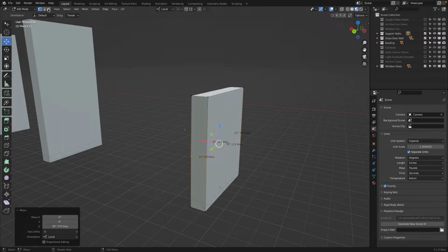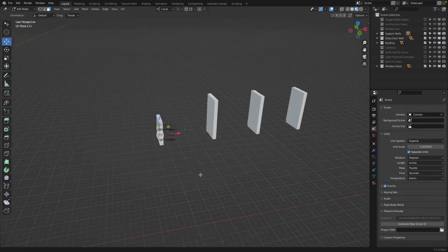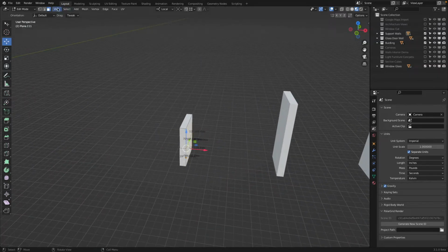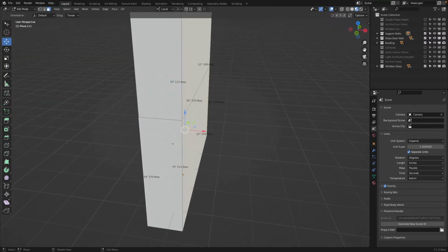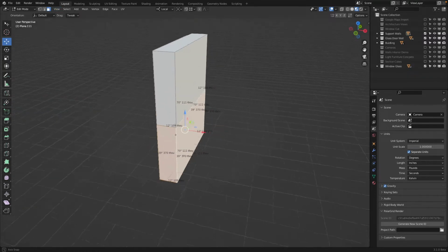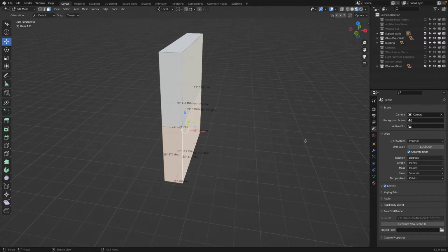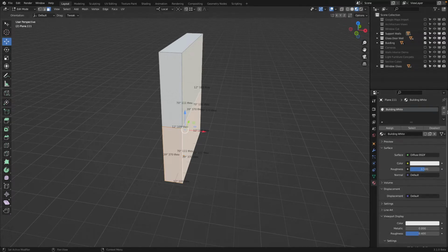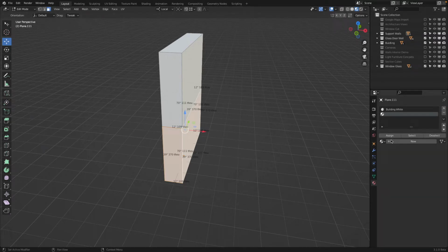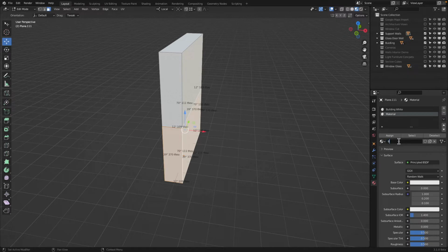Switch to here. So this is the material preview. Then I can select, whoa, careful, these materials. Let's go view frame selected, so the rotation is better. And now this I would like to give maybe an orange material. There, plus, new, we call this building orange.